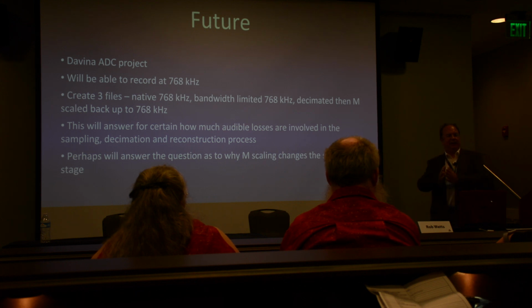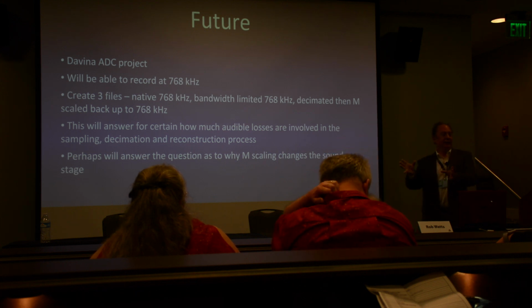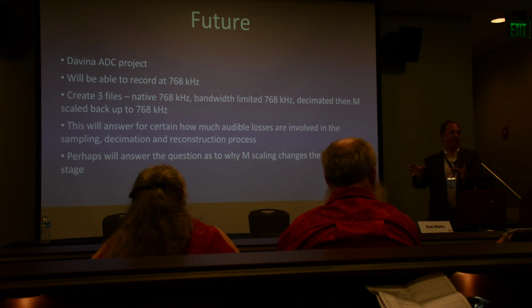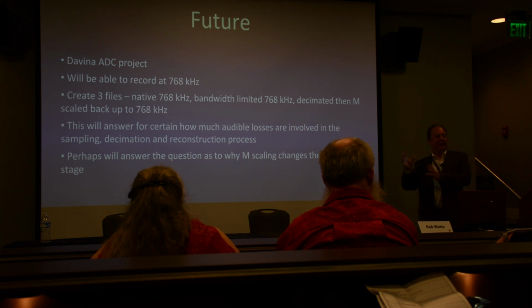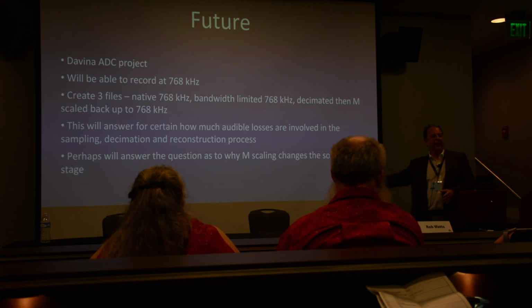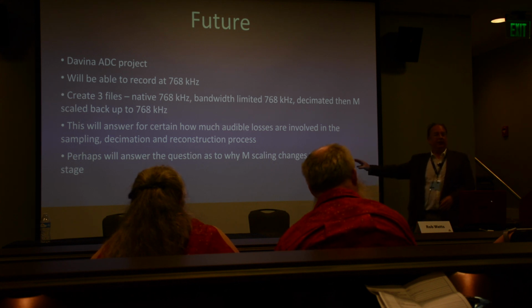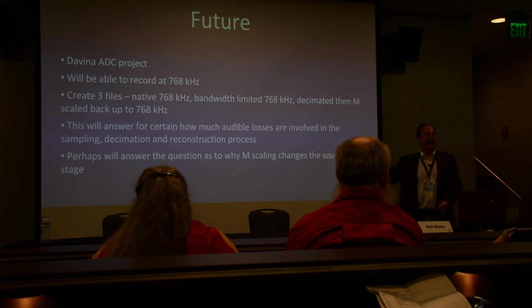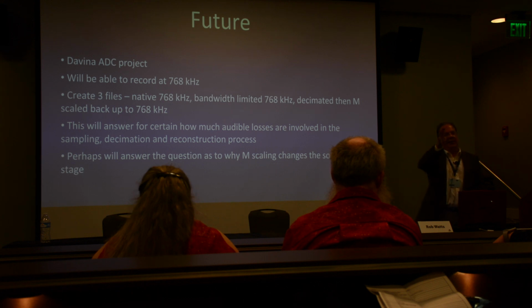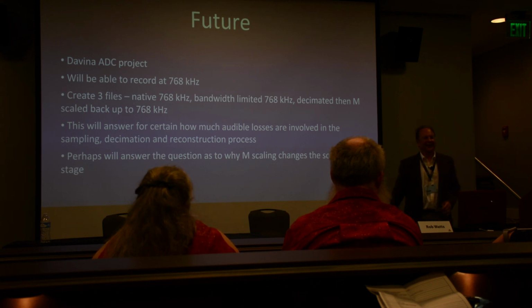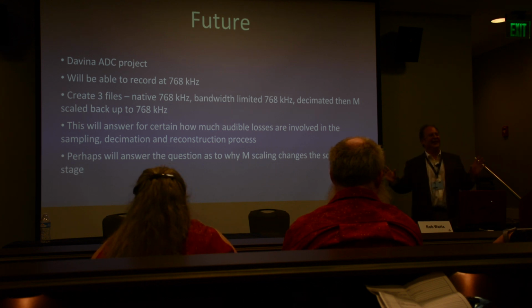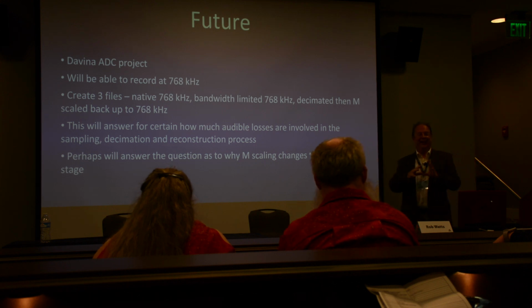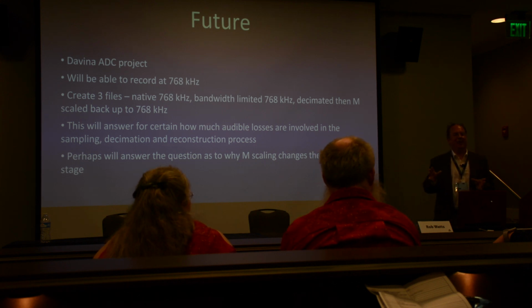And that gives you 16-bit reconstruction performance. Does that imply that we need to be 18-bit or 20-bit or 24-bit? If you want 24-bit Sinc Function reconstruction, you need 256 million taps. And it will take a couple of minutes for the signal to go through your DAC. So that's never going to happen, and I doubt very much that's going to be audible.